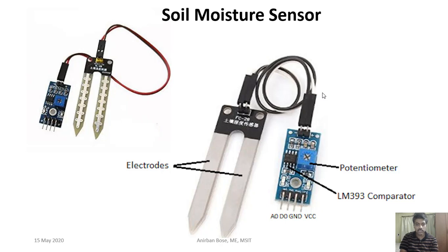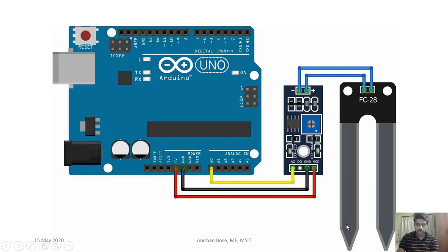Here basically one potentiometer is there that will adjust the intensity, how much you will set according to your choice. And these are the pin connections. You can see it can be both analog, digital, ground and VCC. And the connections to the Arduino are almost similar for almost all the sensors. One will connect to the pin, another one is power, another one is ground. Okay.